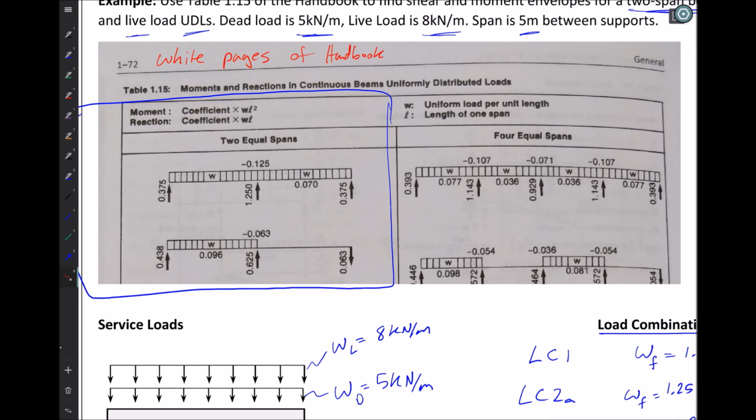So thinking through how a shear diagram would look for this particular beam that we have here, our reaction would jump the shear diagram up, and then we would follow down with a linear slope until we hit the other reaction. And the slope of that is the magnitude of W. And then we would jump up by a value of reaction here and follow back down and go back up to 0. Now in doing that, we would see that the jump that we took in shear, or the change in shear from this location down to where we are over here, is simply equal to the area under our load curve. So we'll use that knowledge to find the value of shear here, the value of shear here, and the value of shear here.